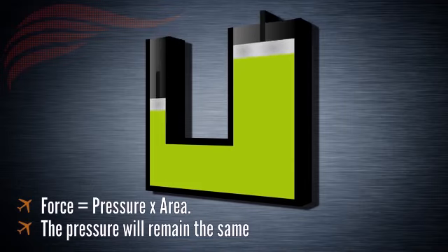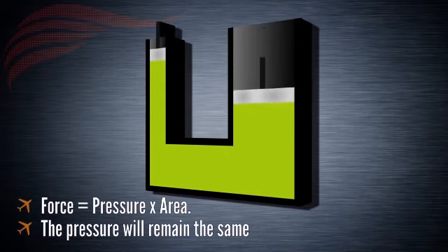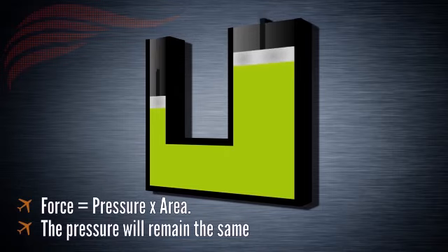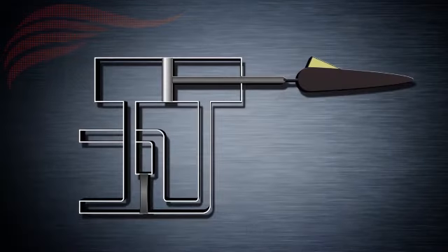They allow us to multiply forces and apply them to control surfaces and other equipment that would otherwise be far too heavy to move. Let's put this into context and look at a very simplified animation of hydraulics moving an elevator. This is a very generalized diagram and is not intended to reflect the architecture on the 737. It's just to put all this physics and maths into context before we move on to talking about the 737 hydraulic system.